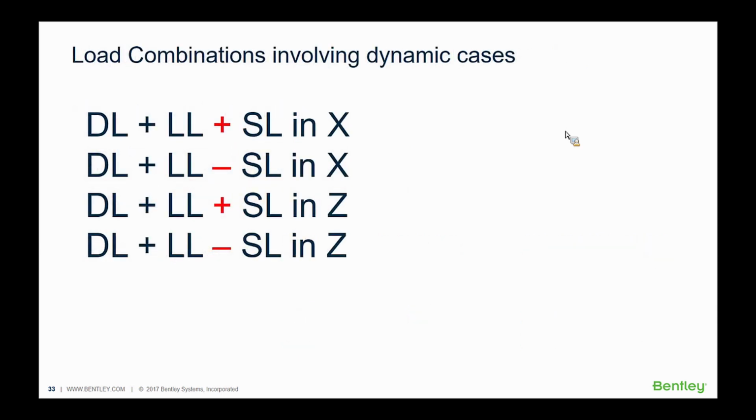Finally, the load combinations. Just be mindful of the fact that seismic force is reversible. So always ensure that you create a set of load combinations where seismic load is added to the other loads in one set, and in the other set, ensure that it's subtracted from the other loads.